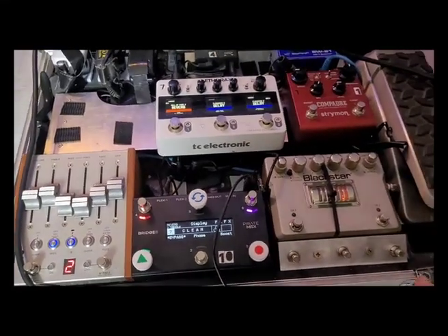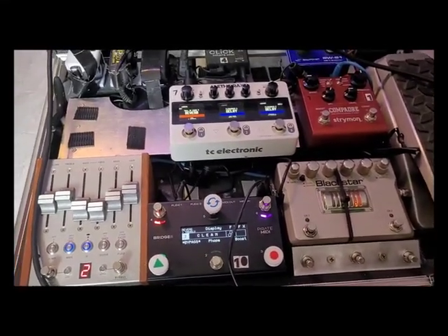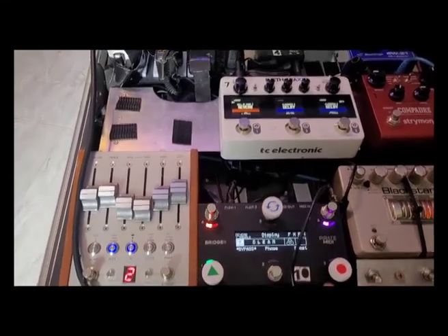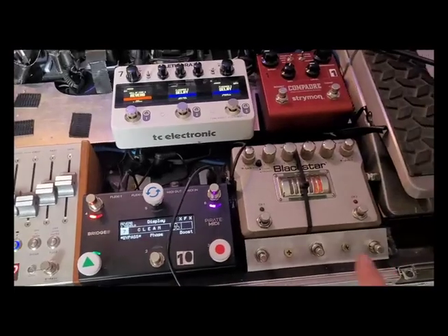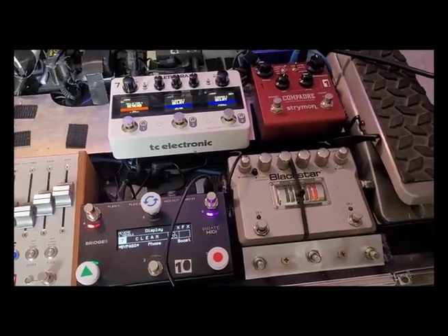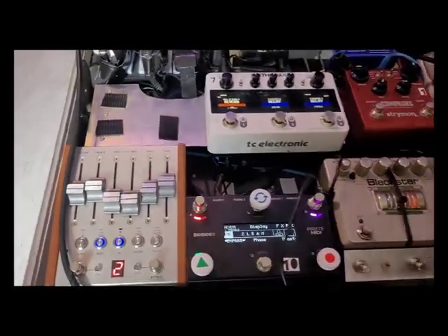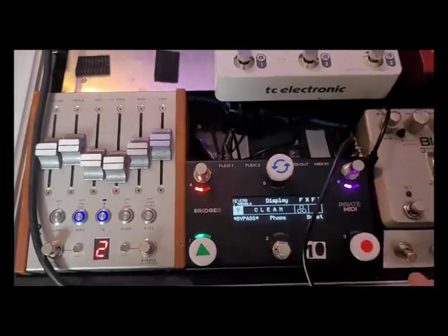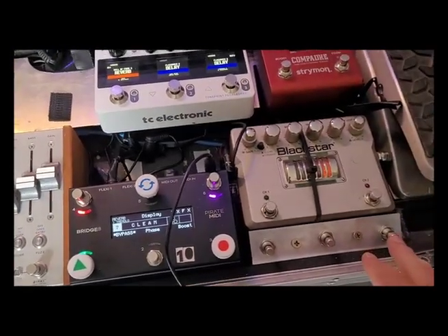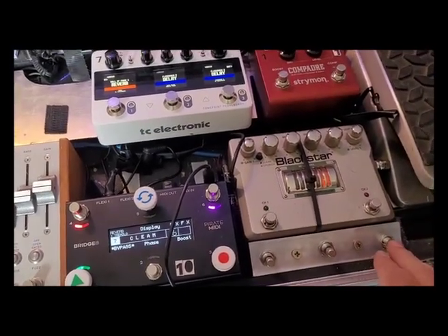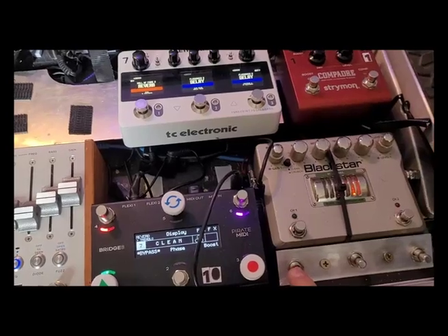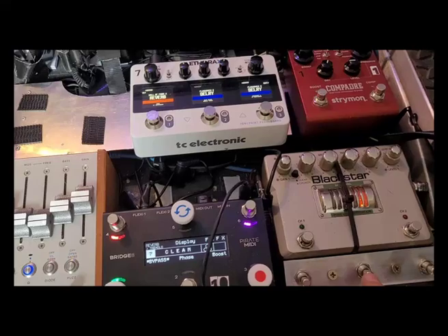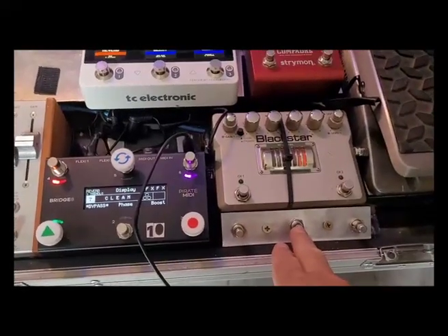How to set up external auxiliary switching for a Pirate Midi Bridge control. This is a Bridge 6, and I have 3 external momentary switches connected through a TRS cable to the Flexiport 1 port of the Bridge 6 controller. One switch is connected to the tip, one is connected to the ring. It could be ring and tip, I can't remember. And the switch in the middle is common.